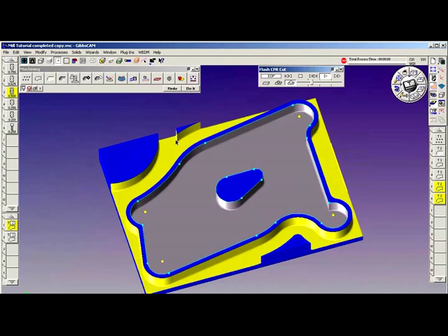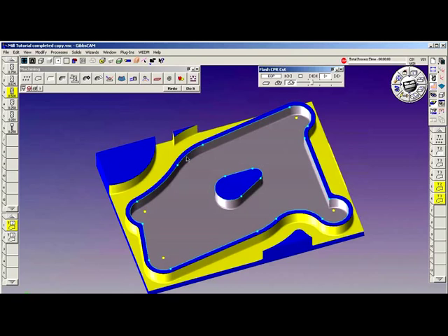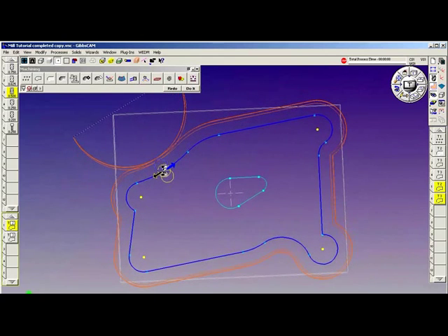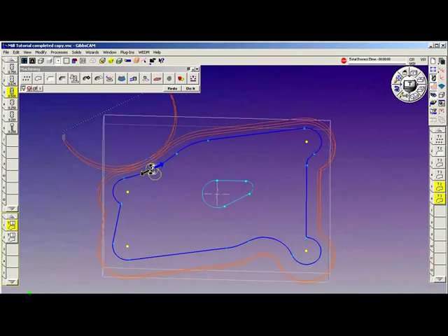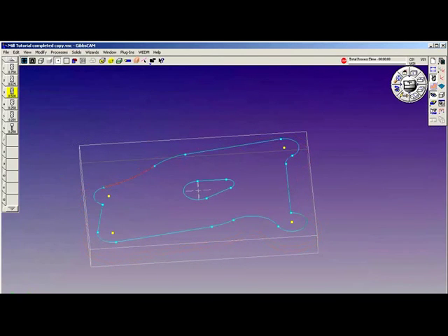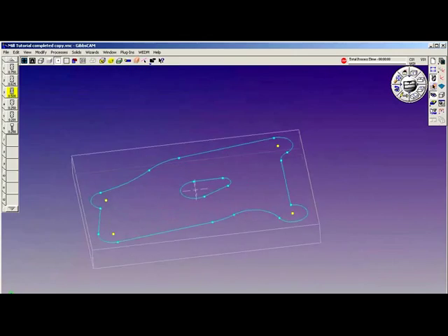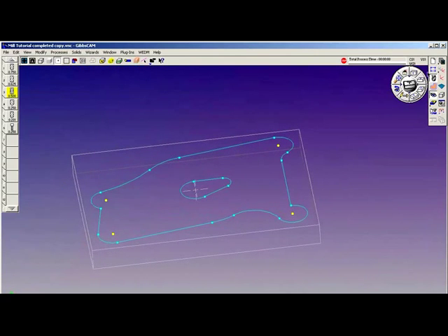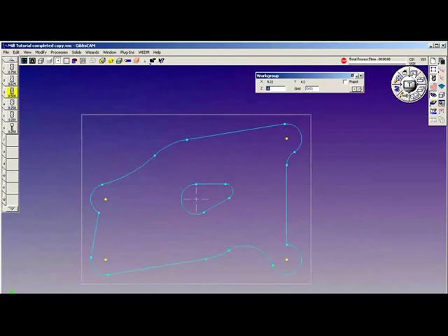This extra material is going to be removed by first drawing some geometry on screen using the mouse tool and then doing a contour cut on that geometry. Let me illustrate how to make mouse line geometry. Turn off my CAM palette so I don't inadvertently bring my markers up. Open the geometry creation palette, line and mouse line. Now, top view.